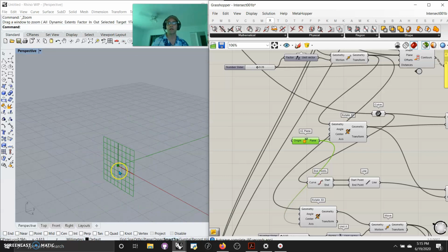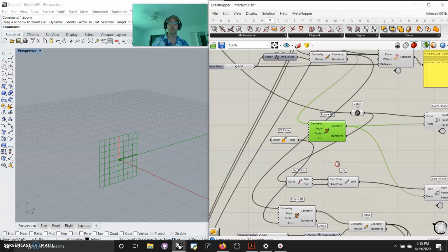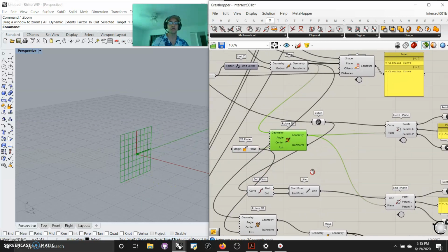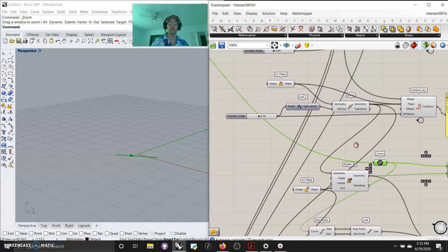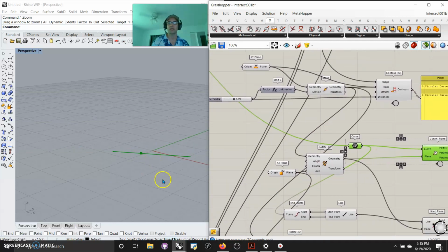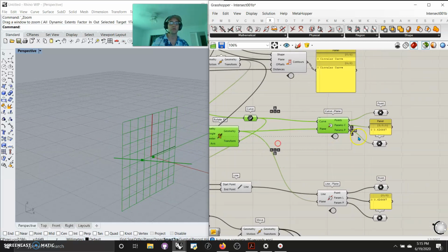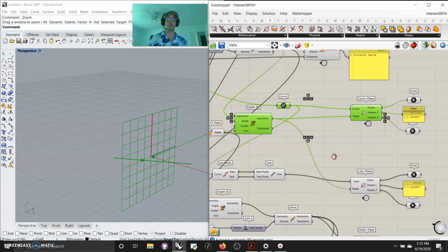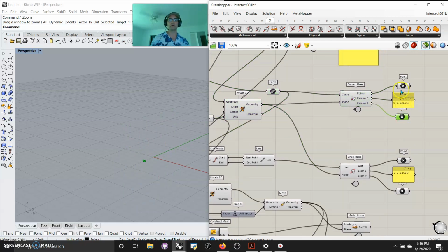So what do we do to do that? We set up a plane. I actually chose a plane on the XZ plane, and I brought that in as a rotation and rotated it back. That will be my plane that I take my points and my curve, and basically that curve that I used from an earlier script, one that we extended by scaling larger. It shows me where that plane and that line come in contact with one another. Pretty darn simple, and it actually gives you the parameter of where along that line, reparameterized between 0 and 1, it is.